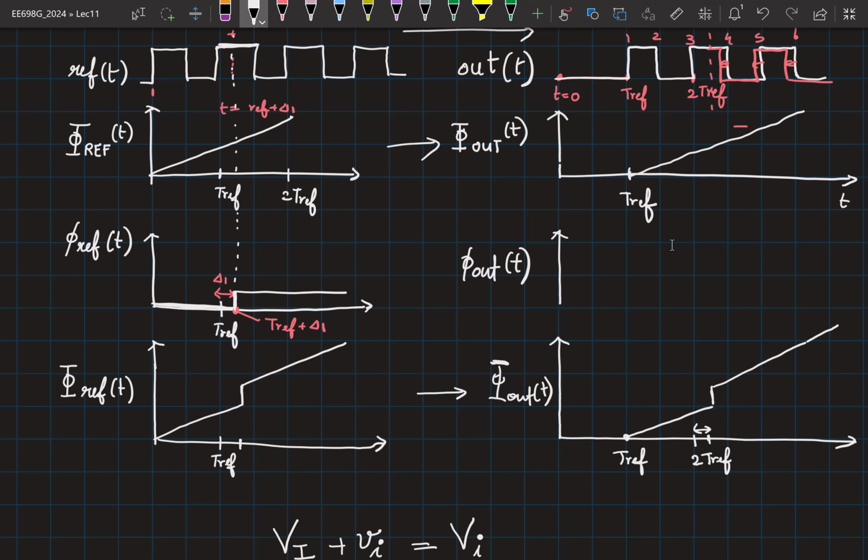Now at this point, even if the signal advances, because it is a square wave, you will not see anything at the output, correct? So a nice way to think about this is, you would expect to see these rising and falling edges, assuming we are dealing with a 50% duty cycle square wave. You would expect to see these happening whenever your total phase crosses 2 pi. So whenever it crosses multiples of 2 pi, you see a rising edge. When it crosses odd multiples of pi, you expect to see a falling edge.